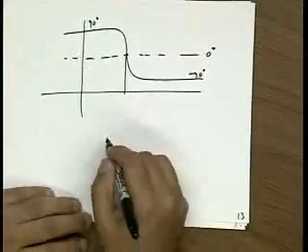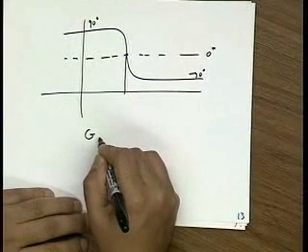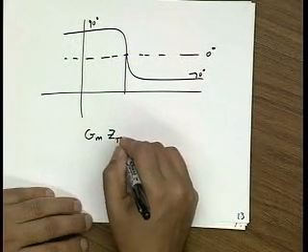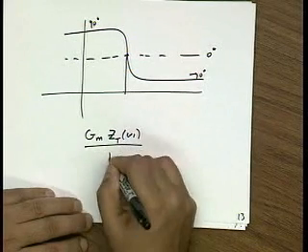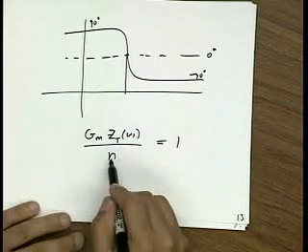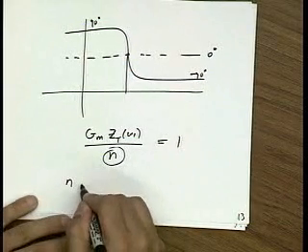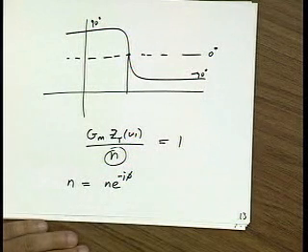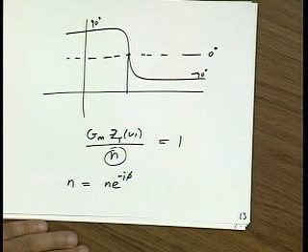Now remember, for steady state oscillation, I need this equation to be equal to 1, right? And let me imagine now that n is actually n e to the minus j phi. So there's some phase delay going through the feedback circuit.